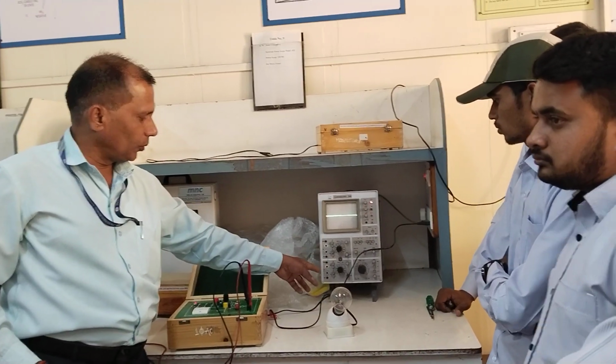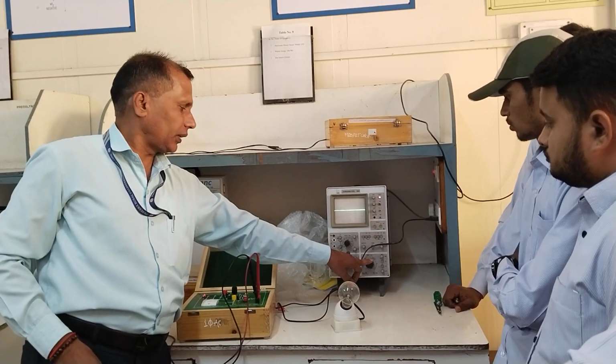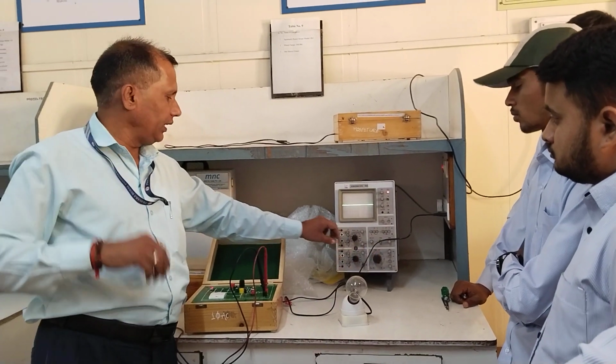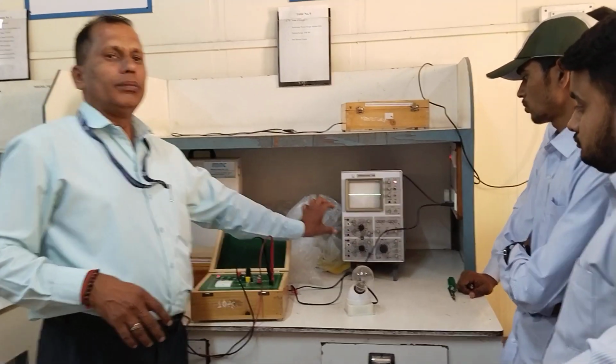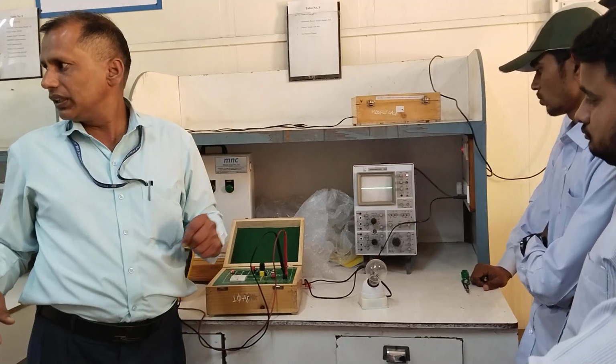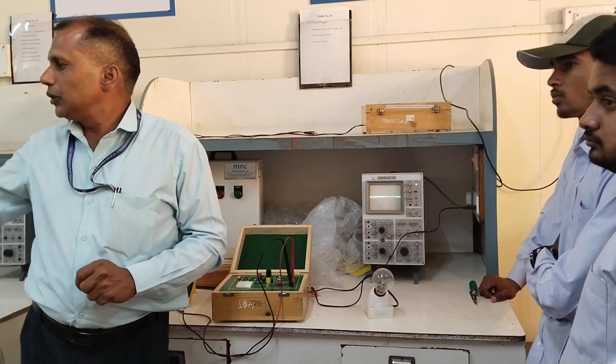Okay, channel 1, channel 2. This is time, and you can measure the time divisions and multiplication factor of time, and thereby you can calculate T, and thereby you can calculate F. So now here you can have a measurement of voltage and observation of the signal.